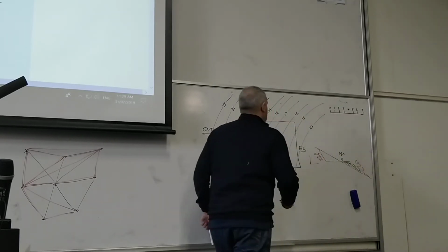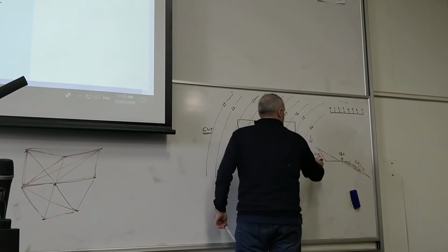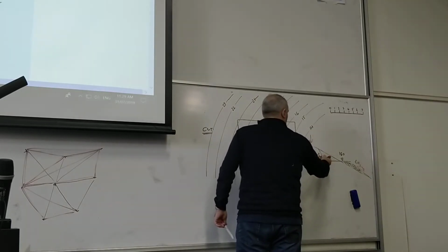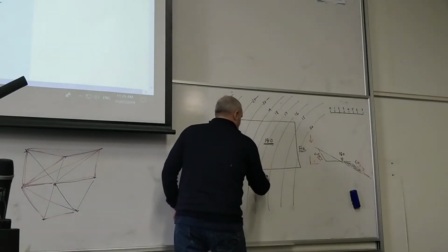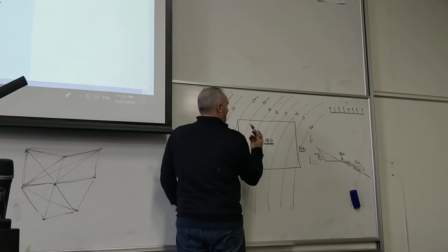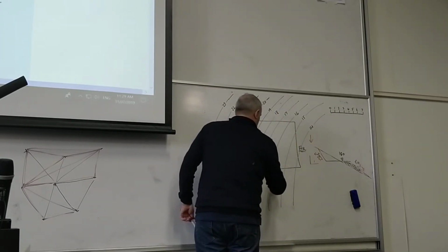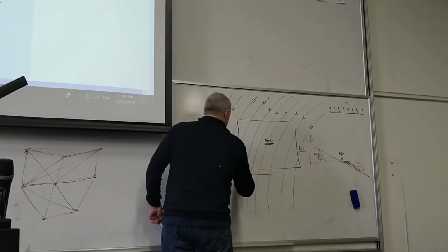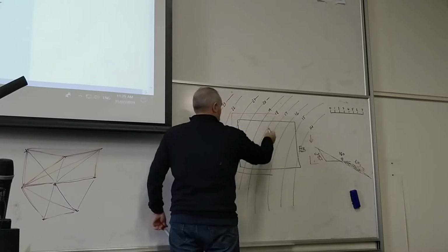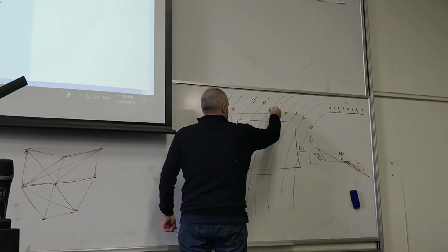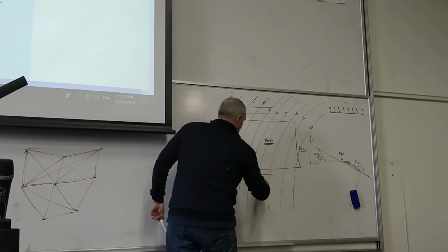Right. So in this case, looking down in plan view on this, our contour interval is 1 metre, so that means every time we go off 1 metre from here, we're going up 1 metre. So let's look at that division there. Let's start drawing from about here. Let's offset 1 metre. Now I know some of you are going to go, oh, that's bigger than that. Just ignore that at the moment. It's my bad drawing, but I'm doing my best to demonstrate this.